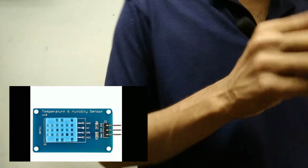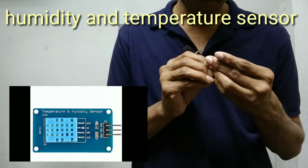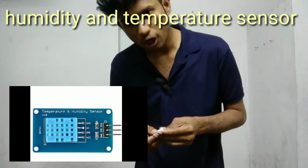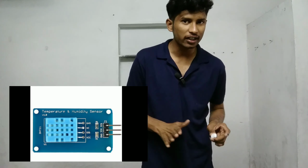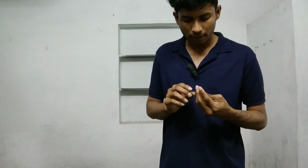And coming to the next sensor, the humidity and temperature sensor. This will have only 3 pins: positive, negative, and the output pin. Positive will be connected to the 5 volts of the Arduino board, negative is connected to the ground of the Arduino board, and the out will be connected to one of the digital pins from 0 to 13 of the Arduino board.